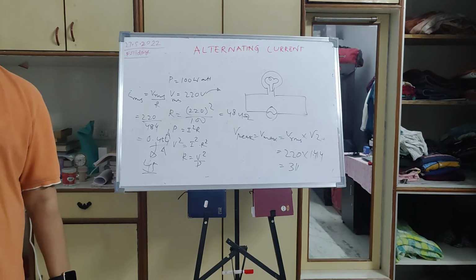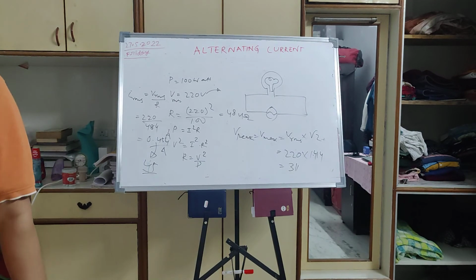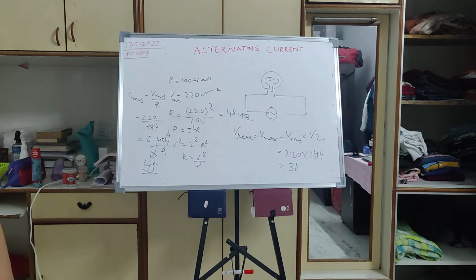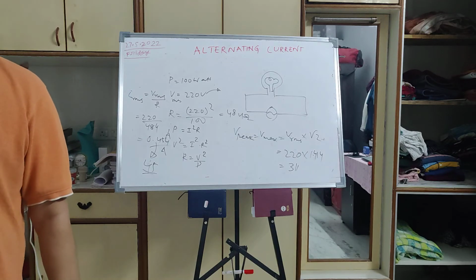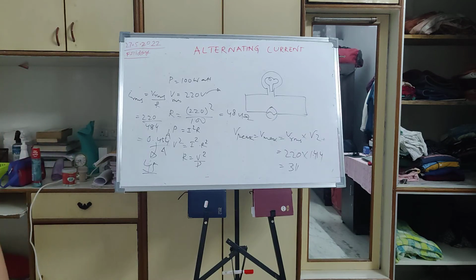At any point of time, the wattage consumed should not be more than the rated wattage. By chance, you might have seen that when you switch on many devices, more than the wattage of your battery inverter, suddenly there will be a trip. Like when you unknowingly put on the electric iron, suddenly there will be a trip because the requirement is more than the supply.